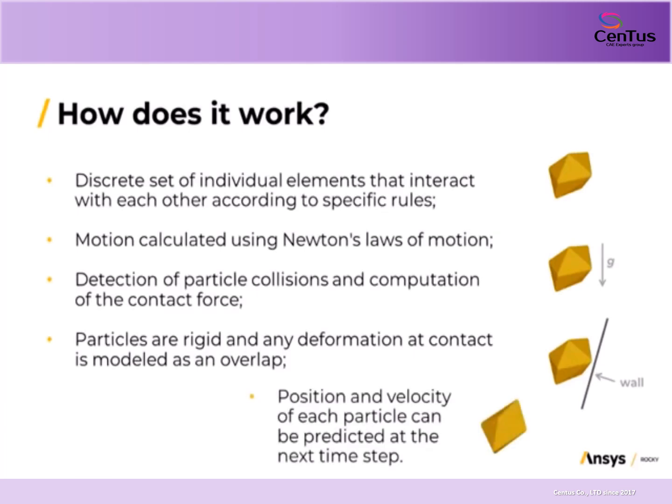With the forces computed, the position and velocity of each particle can be predicted at the next time step. And, in cases where particle breakage needs to be considered, this can also be incorporated into the simulation.